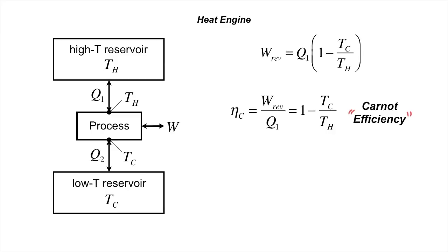What we're saying here is that even if our process is 100% reversible, only a certain fraction of that heat is theoretically recoverable by any means. Thus, Q1 is probably an inappropriate benchmark for defining efficiency. Instead, the relevant benchmark for a heat engine is Wrev. That was a monumental realization to steam engine designers in the 1800s.